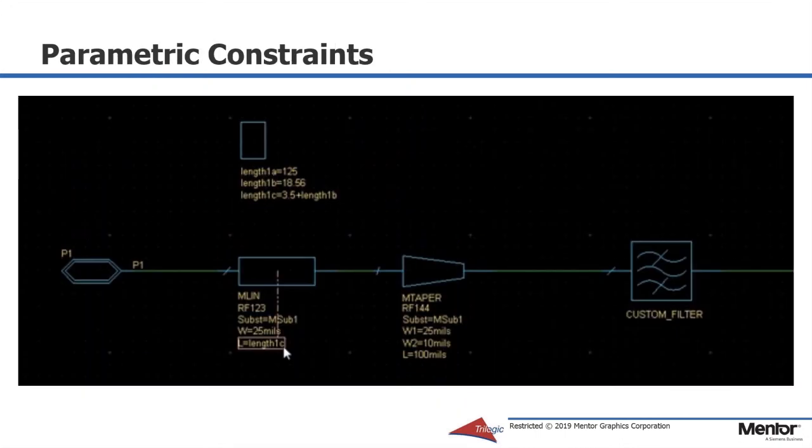So constraining the electrical and geometric qualities or parameters is another way to assure optimal impedance matching between the radio and the antenna. And here you see an illustration of parametric constraints that you can enter in Designer, where you can actually define each trace if you want, and you can define radio and microwave stubs and links and components so that it constrains really the electrical behavior to what you've defined on the screen. It's just another way to avoid mistakes and oversights in layout prior to going into layout.